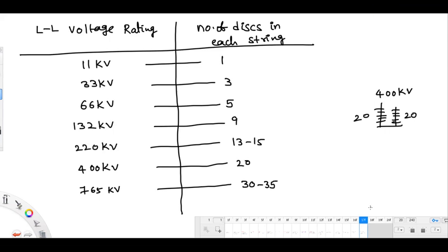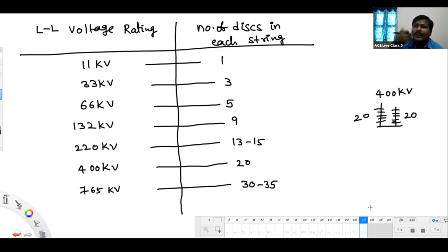Okay, sir. Sir, in the electrostatics class, you said that R is less than 0.368. Smaller. Sir, in that, if you want to design the same conductor, do you use the safety factor, sir, or else can we add it? Yes. Always, after finding the electric field intensity on the paper, you should multiply with the safety factor to go for the dielectric material selection.